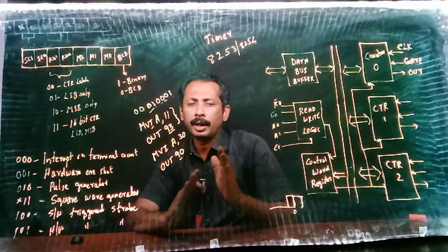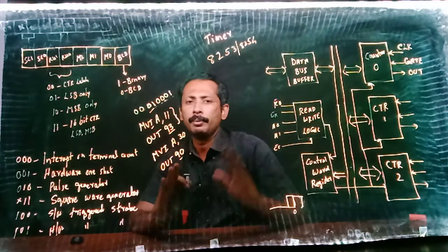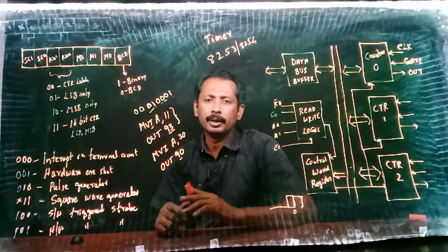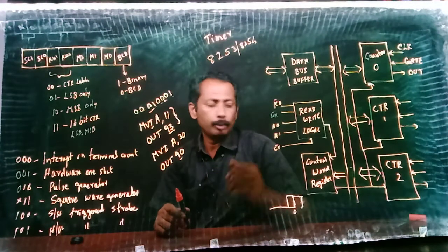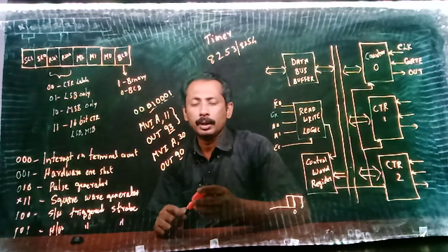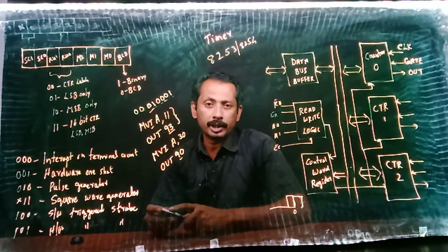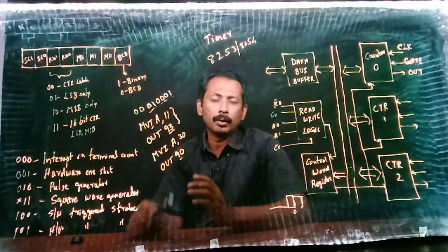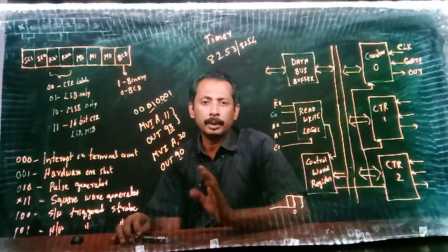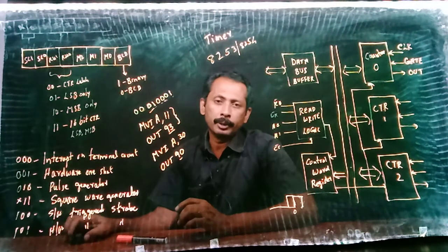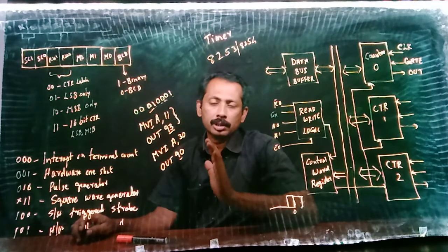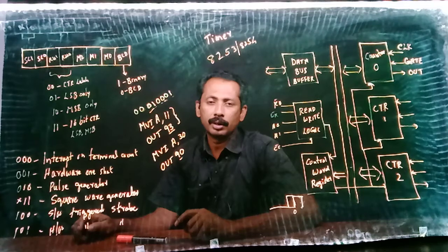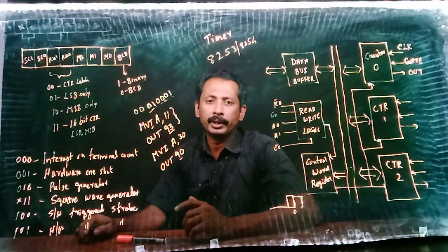അതായത് ടൈം ഇത്ര ആകുമ്പോൾ അറിയിക്കാൻ ഒരു ടൈം കീപ്പറെ ഏൽപ്പിക്കുന്ന പോലെ. This IC can perform a time operation. So the MPU is relieved of time keeping. The MPU can do some other operations. It can load the count, then depending on the clock and gate inputs, the counter gets decremented, and when the count reaches 0, the state of the output changes. Okay, so see this video again for better understanding.